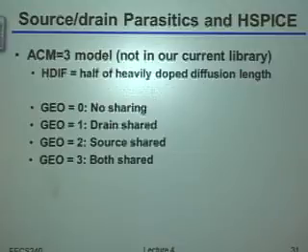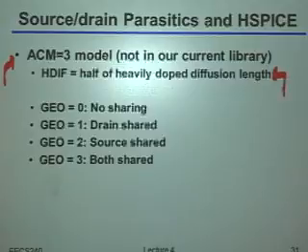So for example, if your model has a so-called ACM equal to 3, and I'm not actually sure what ACM stands for, I think it's automatic capacitance modeling or something like that, then SPICE tries to intelligently figure out what the layout actually looks like without you explicitly saying what AS, AD, etc. actually are. Now, there's an additional parameter you need to add into the model in order for it to have something to calculate these numbers on.